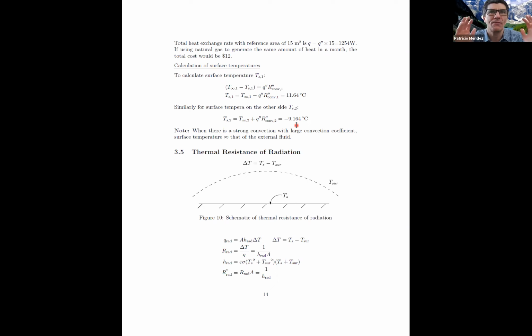Because this convection on the surface became secondary. And whatever you do to it, it doesn't matter anymore. For those of you in MARI, the solution, you know what it was? To make alloyed steels that would become hard, would turn into martensite at slower heating rates. But heat transfer had reached its limit.